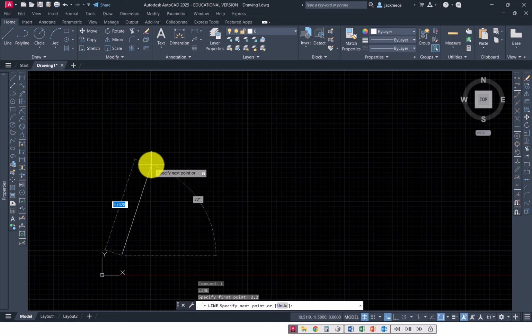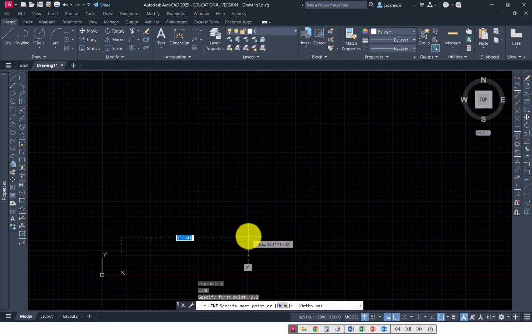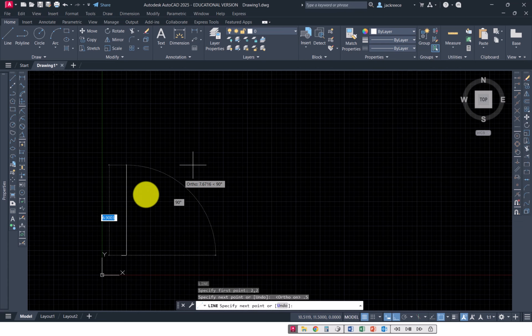If you look at this exercise 4.1, it tells you where to start, what direction to draw, what dimensions to draw these things in. We'll turn on ortho mode, so F8 on the keyboard, and then we'll just use direct entry to work on some of these things, since they're all perpendicular to each other. So it's 0.5, 0.5, and then we're up 0.875.